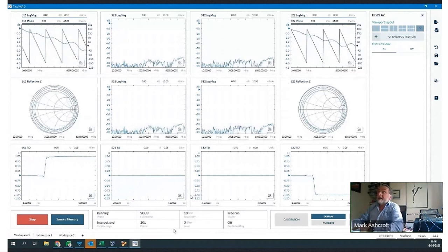Yes, indeed we can, and still there doesn't seem to have been much change. So quite quickly, I've set up quite a complicated display. I've got multiple time domain plots, dual axis plots, Smith charts, and I've got all the information in front of me, and I can quickly change the parameters to see that my measurements are all good.